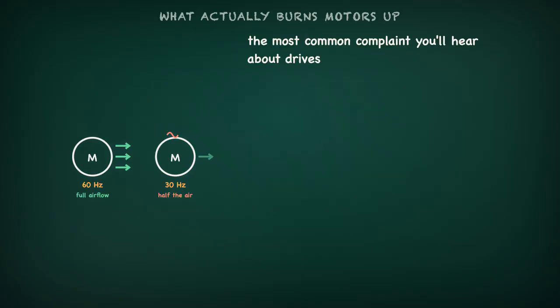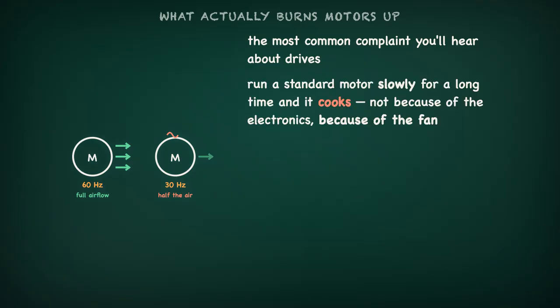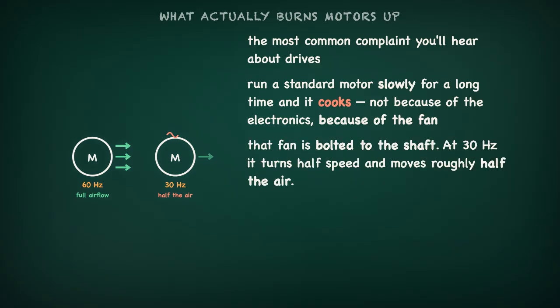Now, the thing that actually burns motors up, and it's the most common complaint you will ever hear about drives. Run a standard motor slowly for a long time, and it cooks, not because of the electronics, because of the fan. That cooling fan is bolted to the shaft. Slow the motor to 30 Hz and the fan is turning half speed, moving roughly half the air.